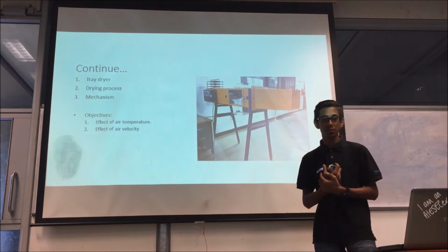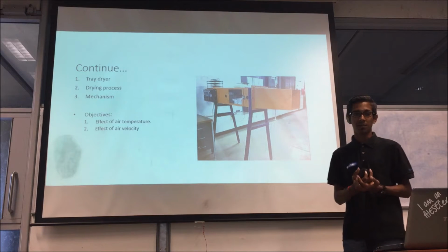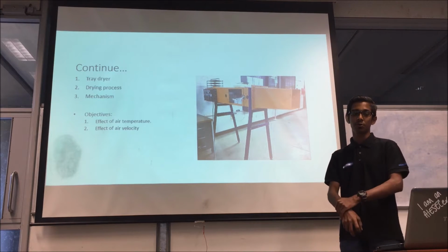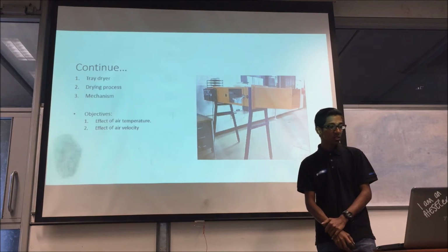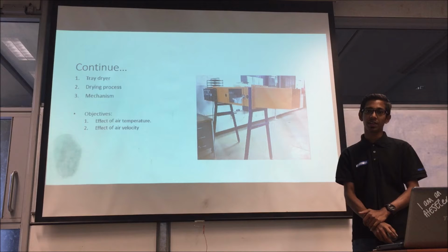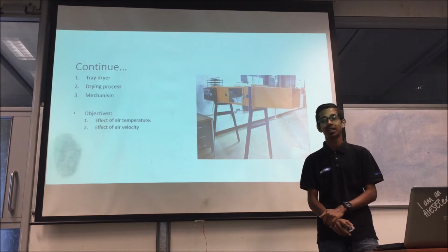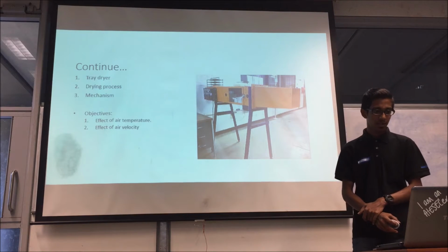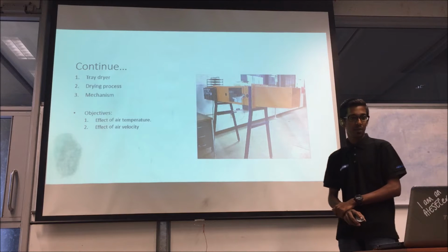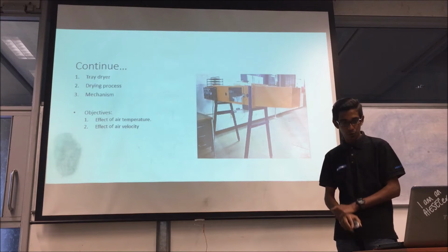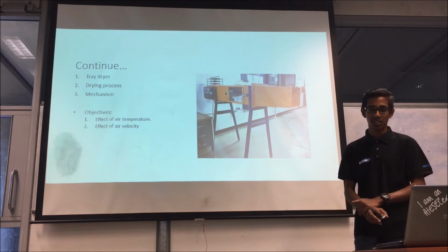Next, the equipment used in this industry would be the tray dryer, and therefore it is ours too. This equipment is widely used in the food industry to replace the traditional method of drying. In the laboratory, the equipment comprises an air duct mounted on a floor standing frame to give a comfortable working height for the operator. Air is drawn through the mesh guard by a motor-driven axial flow fan impeller whose speed can be controlled to produce a range of air velocities in the duct.